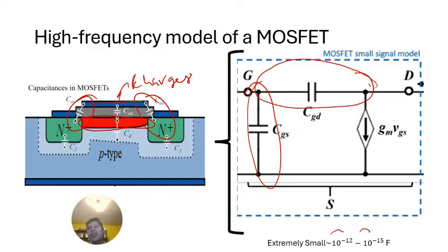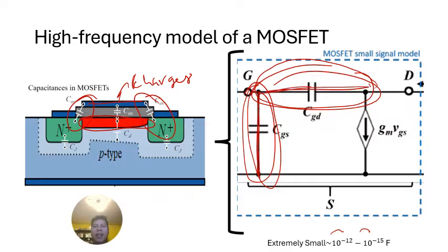So as it turns out, there's a nice range where we can assume that the external capacitors are short while still treating the MOS capacitances as open. But if we keep increasing the frequency, eventually these MOS capacitances will start behaving as short and our amplifier will stop working. So as a result, there is a limited band of performance.